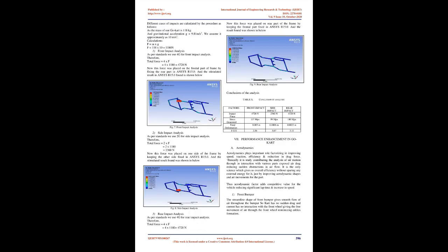6. Analysis. We made our analysis on software named Ansys R15.0. Analysis for a few of the go-kart parts is shown below. A. Stub axle. We have chosen AISI 1040 steel as the material for designing our stub axle. The force is equal to the entire load of the front tires, cornering force of magnitude 1.2 g, and kingpin movement were applied to the respective points while constraining the stub axle in all directions. The deformation and equivalent stresses are stated below.